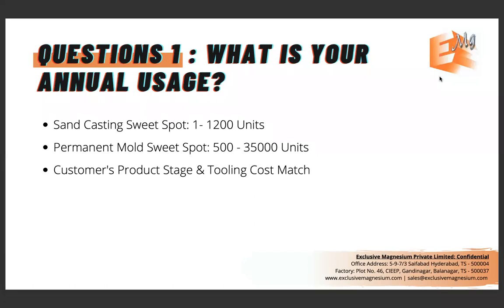If you're just at the prototyping stage and you've not finalized the design, you don't know whether it's going to go into production, you might as well just do sand casting, right? So the client and the manufacturer have to talk to each other to understand what the product stage is and what kind of tooling makes sense.